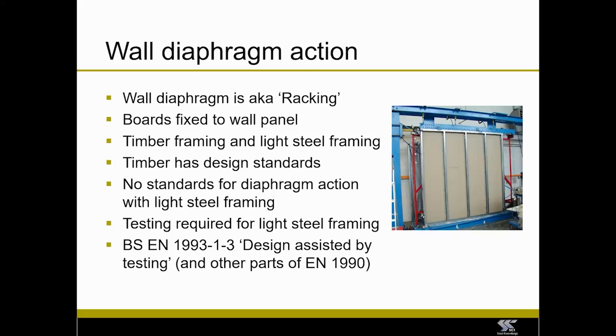As I said, there isn't anything in terms of design standards, Eurocode or British standards, for light steel framing. There is for timber-based frames, but timber-based frames are not exactly the same as light steel framing, particularly the way the fixings are used, the way the fixings are anchored within a timber stud compared to in a thin gauge light steel frame. They all give different fixing stiffnesses, if you like. So that does need to be taken account of and derived from testing.